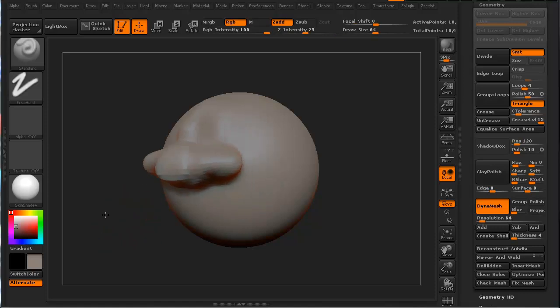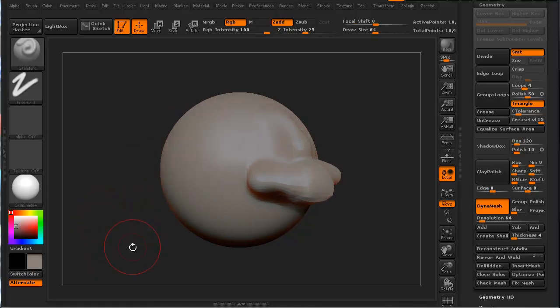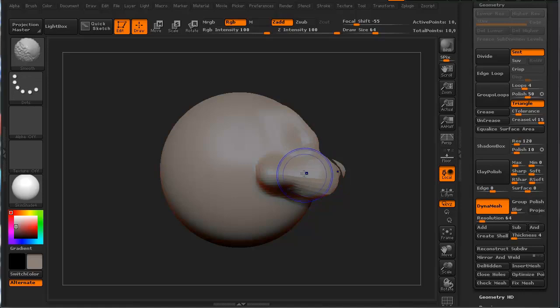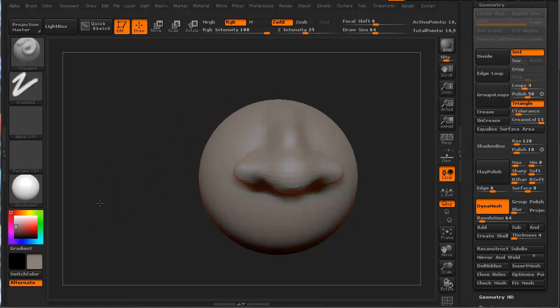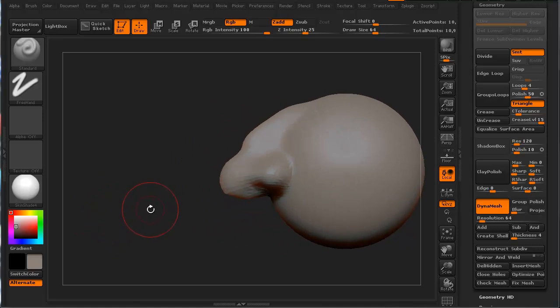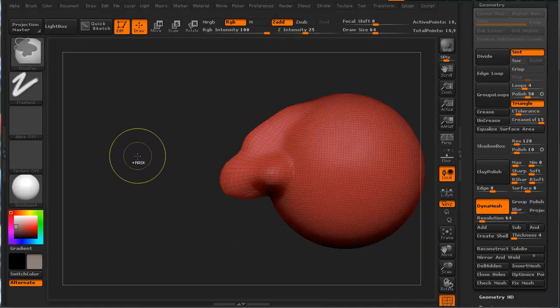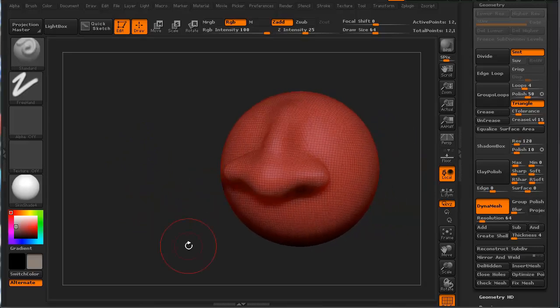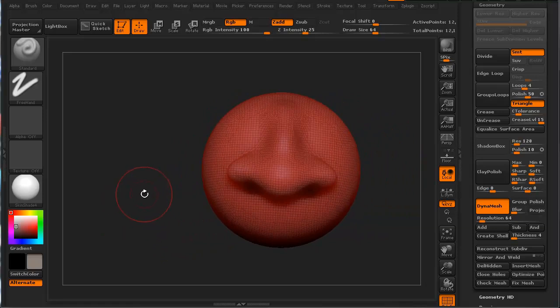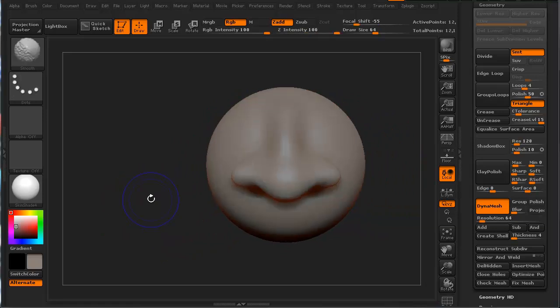Again, all the tools for sculpting that you would generally use on models in ZBrush are also used in the Dynamesh. It's just the same thing. I can hold down my Shift and just blend that down a little bit. Okay. If I hit my Shift F, just so you guys can see it, now I'll hold down my Control and click and drag, and it redistributed that, made it nice and even. So it's now nice and clean. Shift F to turn that off.